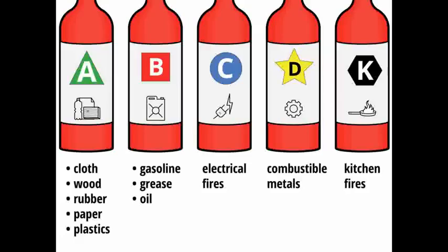Some fire extinguishers are designated with a combination of letters. For example, a fire extinguisher with all of the letters A, B, and C would be suitable for a Class A, B, or C fire. Water extinguishers are only appropriate for Class A fires. Water reacts violently with the other types of fires, and as a result could cause the fire to spread rather than extinguish.